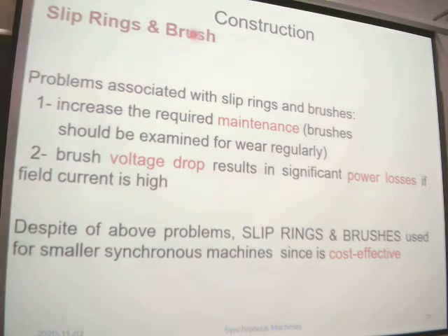With slip rings and brushes, just as with the DC motor, it will require maintenance, and it will shorten the lifetime. And also there is voltage drop on the brushes, so there will be power losses.